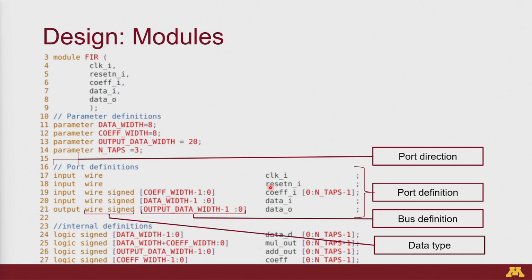One important thing which I'll point out is that Verilog has a 0-based numbering system. All the numbers start with 0, and it's not like something like Python where you have to go 1 plus. If it's an 8-bit number, the counts would be 0, 1, 2, 3, 4, 5, 6, 7. So we would define an 8-bit number as 7 down to 0. You actually define the 2 endpoints of the bus. So an 8-bit number would be 7 down to 0. These are just common things which are a little different, which people may make mistakes on.